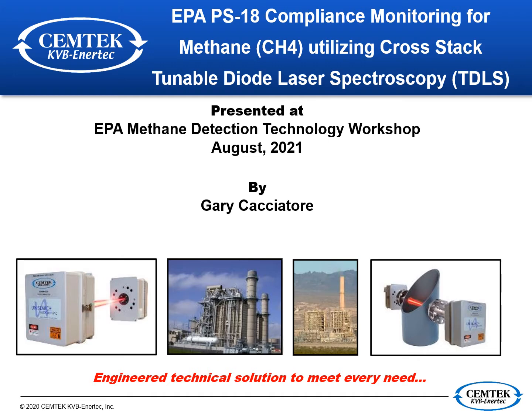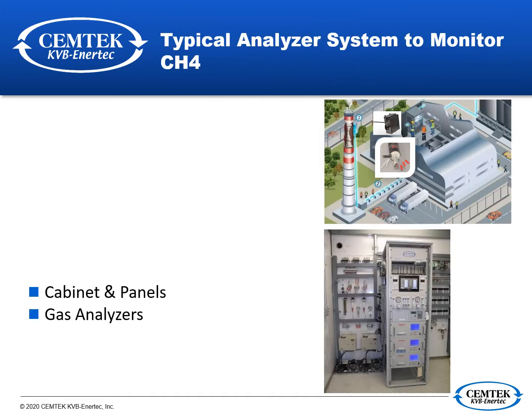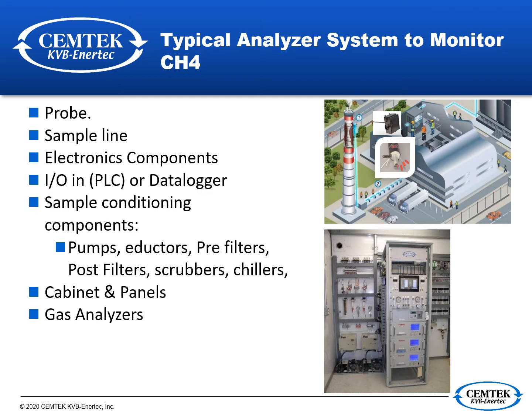Today I want to quickly talk about EPA compliance monitoring for methane utilizing cross-stack tunable diode laser spectroscopy. The typical way of monitoring methane in a process stack or process duct is by utilizing what we typically call a standard extractive continuous emission monitoring system.